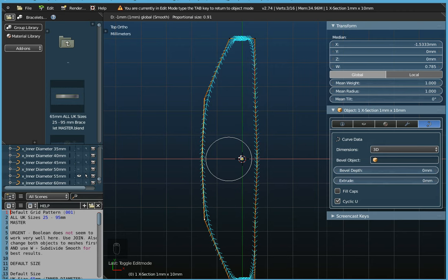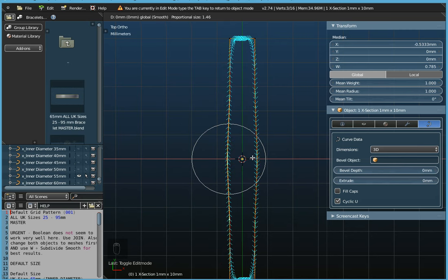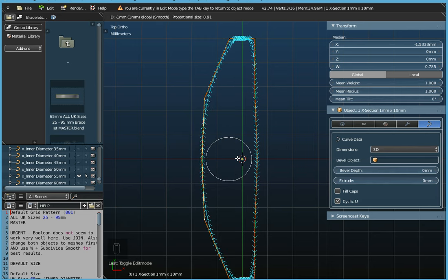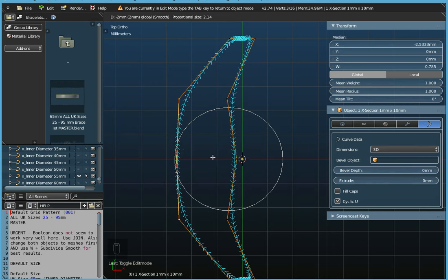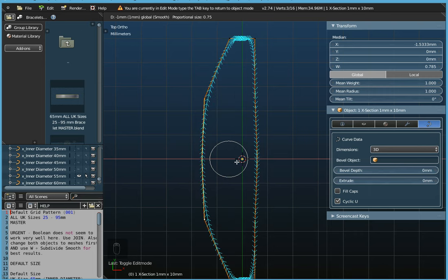Wherever the circle overlaps, that object will be moved in addition to the 3 control points that I'm using. So when the circle is very small, notice only the left part moves. I'm scrolling the center mouse button here. Now the right part moves as well. Well, I don't want to move the right part of the object. I want to maintain that as more or less flat. I just want to move the left part, so I just want the circle small.